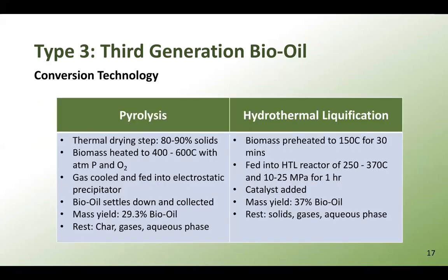So when comparing pyrolysis and hydrothermal liquefaction, pyrolysis requires an additional thermal drying step in order to increase the concentration of solids to around 80 to 90%. So the biomass after that is fed into a reactor and is heated to around 400 to 600 degrees Celsius with atmospheric pressure and in the presence of oxygen.